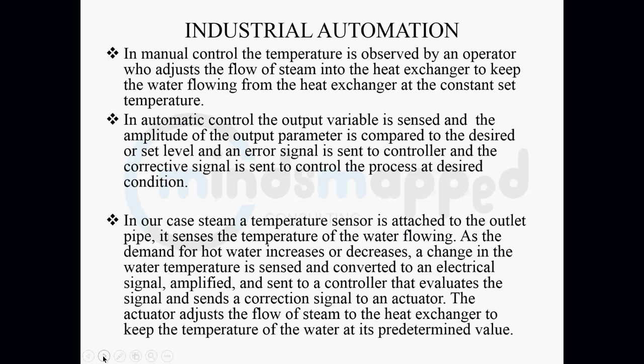So what basically it means is that in automatic control, you're going to put in a controller and a sensor. This temperature sensor will constantly be monitoring the temperature of the hot water coming out, right? The sensor sends the temperature constantly to your controller as an input.